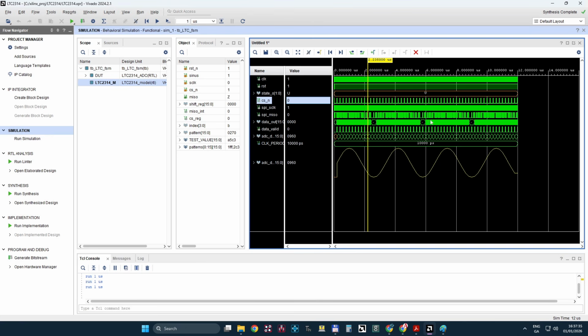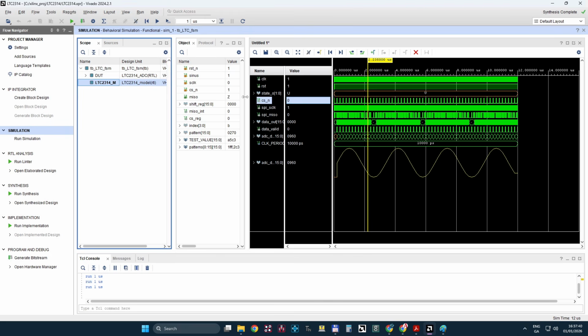It's just this, right? So this block here, the model, is creating this nice waveform. Now I created a model with a signal you can actually force to have a sinus, or you can force to have a constant value. I'm not sure why I did that, what for. But anyway, it's not much. The model is actually synthesizable. You can actually put it inside the FPGA, and play with this without actually having the ADC attached. So you will get this sinus, like a test signal.